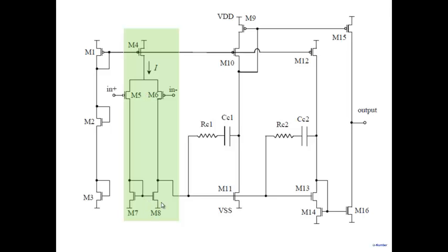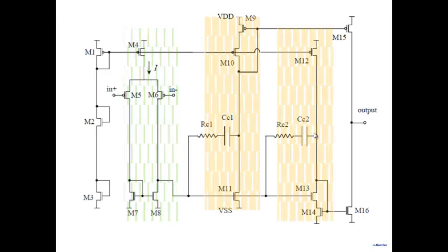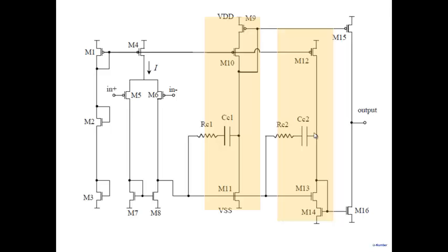Normal differential pair here. What is happening next is they're going to a stage like this. Two such stages are there, so let's focus on these two. Each one of them is actually a common source amplifier. If you look at this one, the signal from here goes into this transistor, a common source amplifier with a load which is given here.